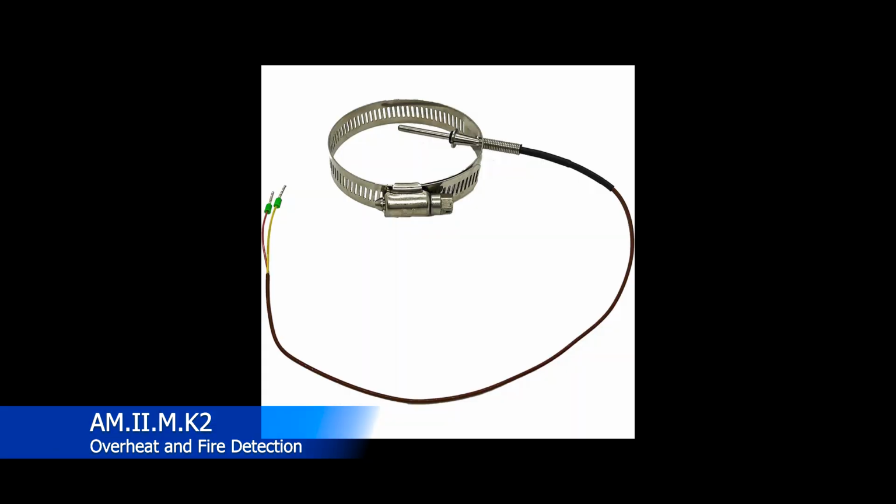Okay, here's a pretty standard example of a thermocouple in general aviation. Whenever you're installing an engine monitoring system on an aircraft, you're going to take the exhaust flange coming off of the cylinder, drill a hole, slide the actual detector in the thermocouple inside of there, and secure it with that band clamp. The thermocouple then has the two wires for our two differential circuits, and that will go into the wire bundle that goes into the rest of the thermocouple system.